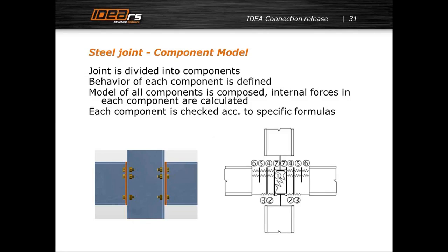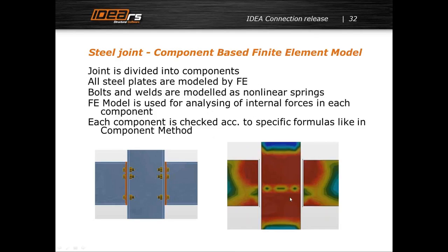And what we did is that instead of this complex spring model, we use a standard finite element model. Everybody uses these finite elements for design of buildings, so why not use them for design of connections?